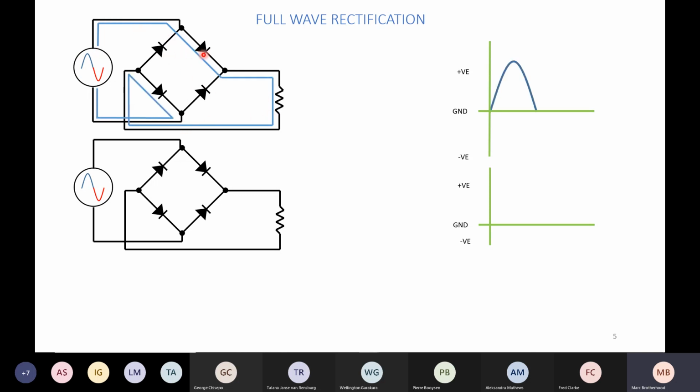It comes down. There are 4 diodes now instead of 1. So the power supply will come down, it'll go through my load. Let's say this load's a lamp, but you don't need a bridge rectifier for a lamp. But let's say this load could be anything that needs a DC voltage to operate. It will come through the diode, go through the load, it'll come up. It can't go through this diode because there's another little blue line that would come down here and block it. So it can't go there, so it's forced to go through this diode.